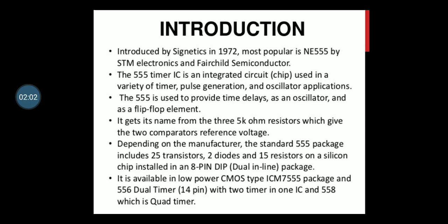This is a monolithic timer IC which can be used for many timer applications such as monostable and astable multivibrators, linear ramp generator, missing pulse detector, automatic battery charger, etc. A single 555 timer can provide time delay ranging from microseconds to hours, whereas a counter timer can have a maximum time ranging to days. The 555 timer is an integrated circuit designed to perform signal generation and timing.